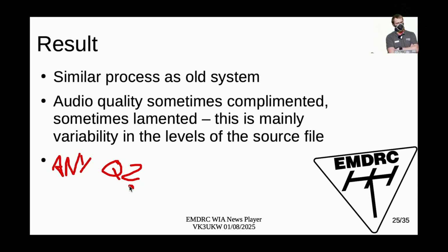Like I said, all recent new radios, since maybe the last 10 years, come with a USB connection. You just plug a USB cable into your radio and into your computer, and you get both a sound card inside the radio that is now connected to your computer, and a serial command channel where you can send text commands to the radio and where the radio sends status information back to you.